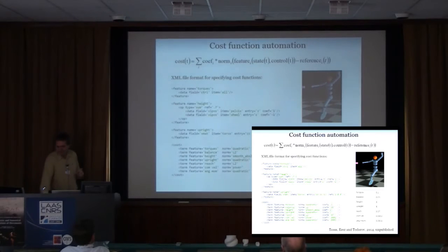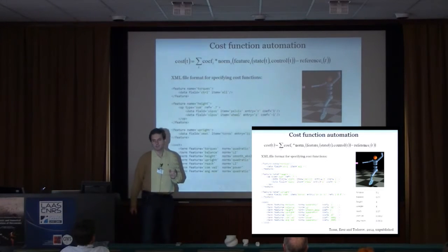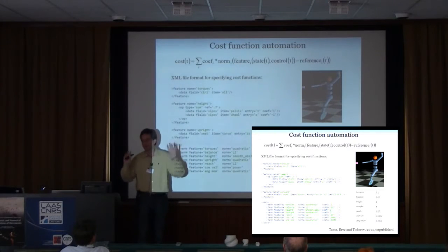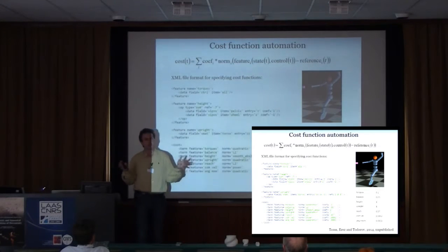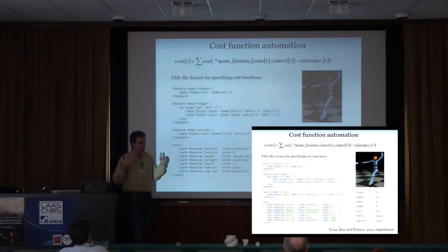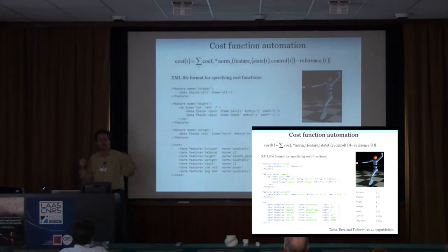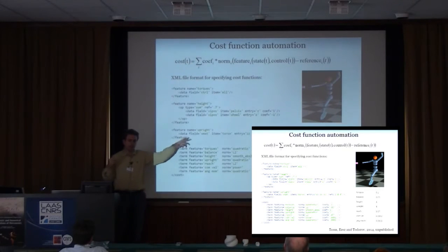Now, one disclaimer here is that getting these things to optimize in real time, you actually have to design the cost function somewhat carefully. In the first set of simulations I showed you where this guy was going over the cross, that was really simple. We said, okay, the cross is over there, put your body over there, I don't care how. And when the optimizer had 1,000 iterations of a Gauss-Newton method to figure it out, it does figure it out, right? So if you want to start with a very simple and high-level and intuitive cost, you have to pay a price in terms of computation to figure it out. If you want your optimizer to nail it in 1 or 2 iterations, then you kind of have to help it. So basically, you have to give it something that's in between a high-level cost function and something more like a heuristic value function.